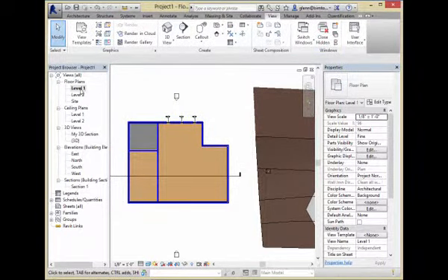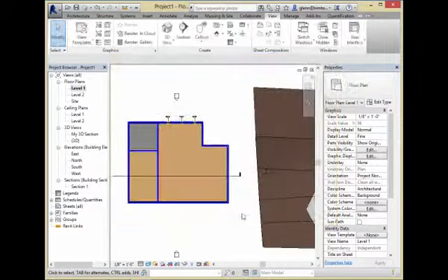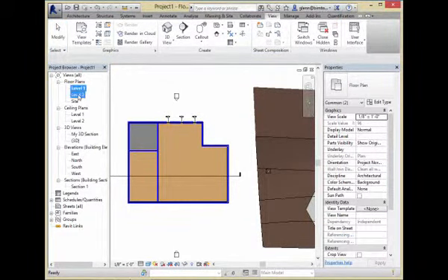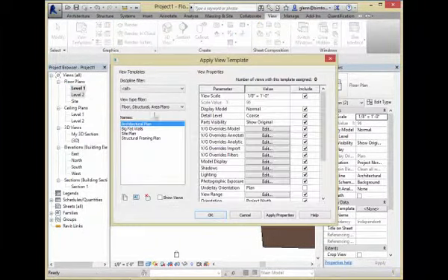So this view right now, if I go over here somewhere, it'll even tell me that it's big fat walls. View name, view template. Actually, it's interesting. It's not actually applied here. We defined it off this, but it's not applied here. If I want to apply big fat walls to this, I can either do it down here and choose big fat walls, or a quicker way, just to let you know, is if you choose them over here in the browser and you right click, you can choose a template that you want to apply.